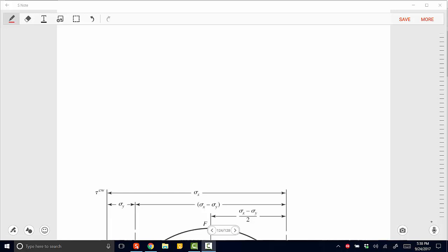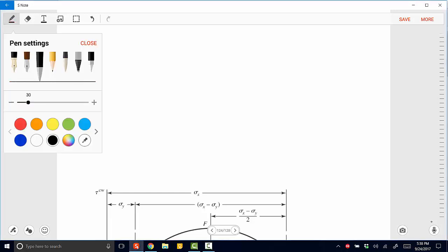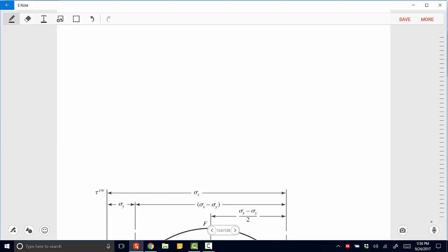In today's lecture we are going to continue our discussion of Mohr's circle, learning how to actually draw the diagram and what the diagram means, and then we're going to do an example of solving for the principal stresses and directions and elements, the extreme valued shear stresses, directions, and elements, and then finally drawing a Mohr circle example of a real problem.